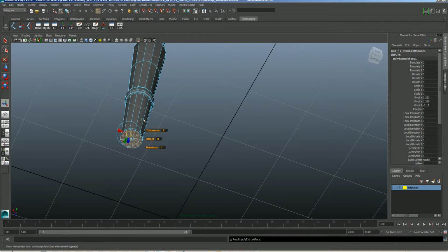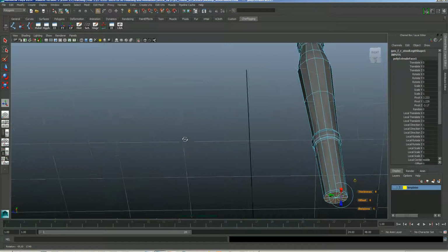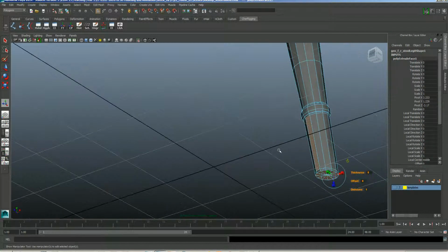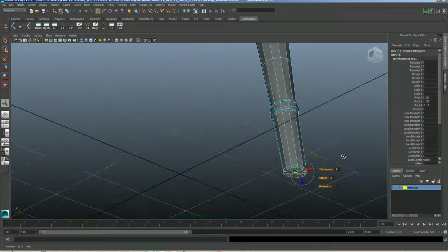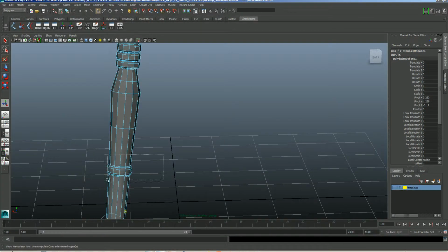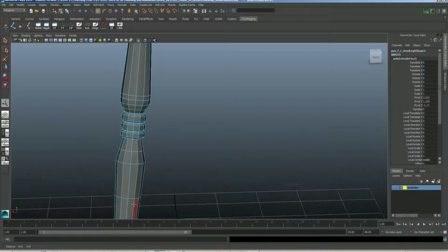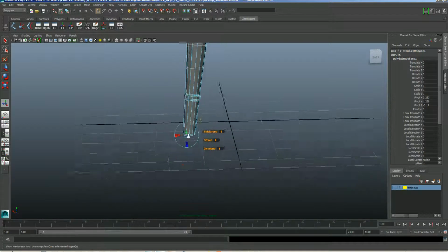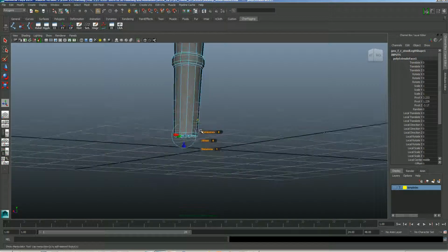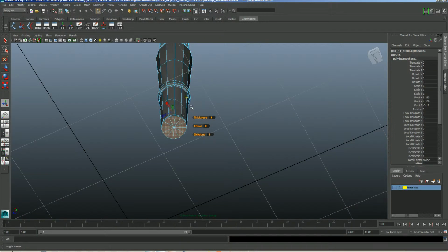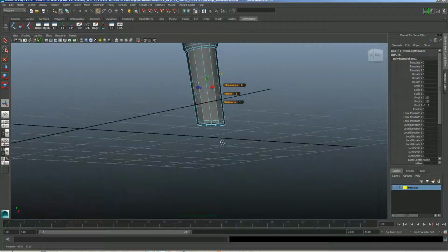With the extrude, I'm going to click into its local mode. Make sure I click on this. I must have another poly selected somewhere. There we go. You can sometimes tell if you click into the local mode and it's not in the center of the selection, then usually something else is selected. So I can control drag around that. Something else somewhere. Might be that one there.